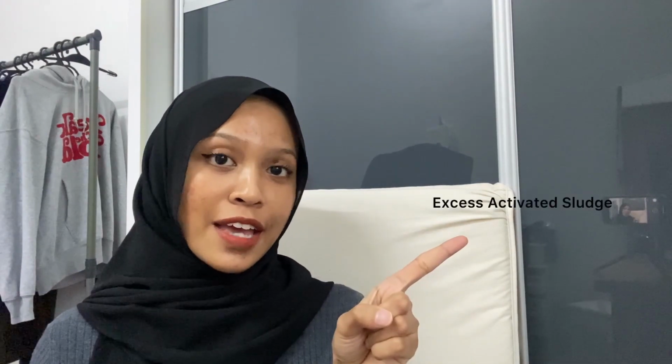The lagoon can receive undigested primary sludge, excess activated sludge, or digested sludge in either an interim process or in the total sludge handling scheme. Normally, landfills are the ultimate disposal location for dried sludge, and this disposal method can be economical depending on the distance from the wastewater treatment plant to the landfill.